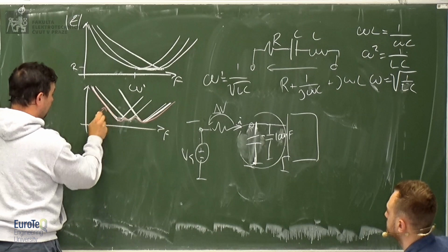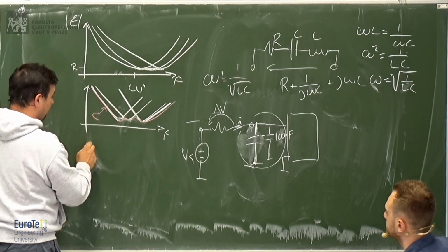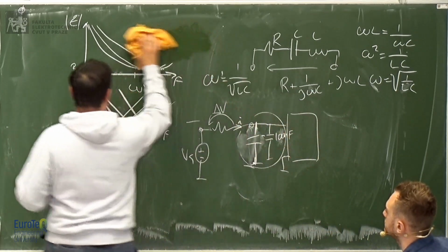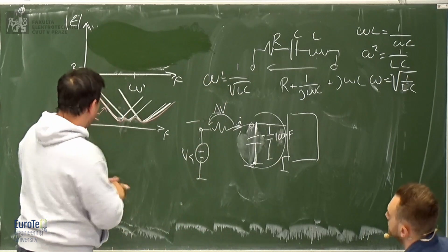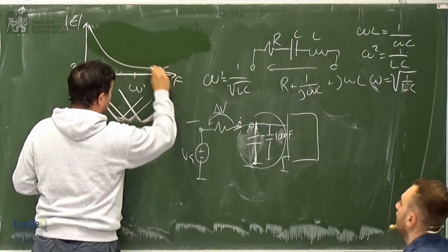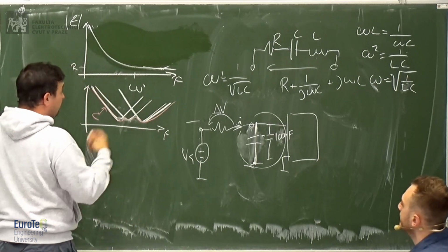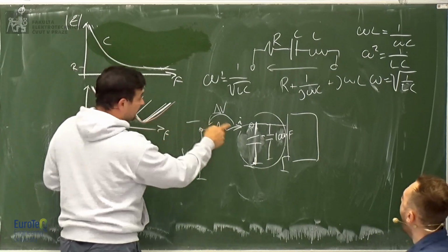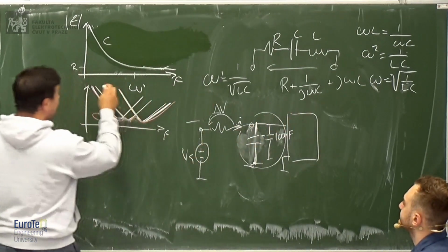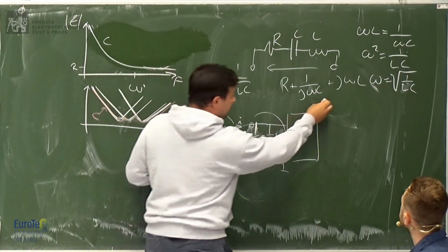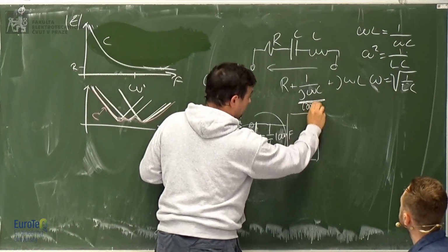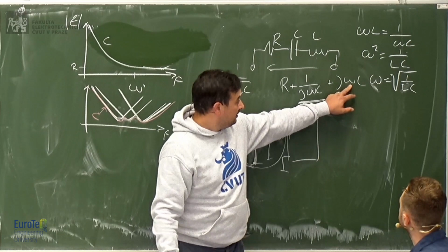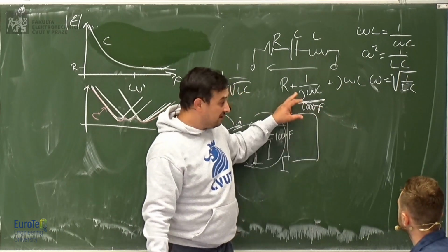Here you have basically the capacitor. Generally speaking, if you have only the capacitor, you would have the impedance going down to 0 without any problem. But you also have the inductor. The capacitive reactance gets lower and lower as you increase the frequency. At low frequency, this dominates, because at low frequency the inductor is basically a short circuit, but the capacitor's reactance is large.